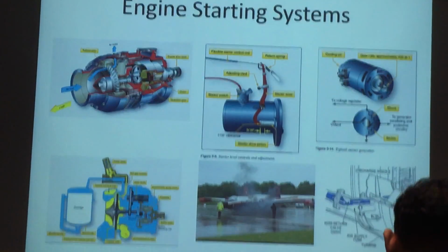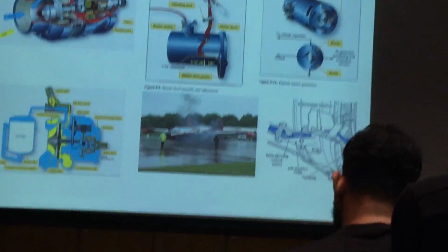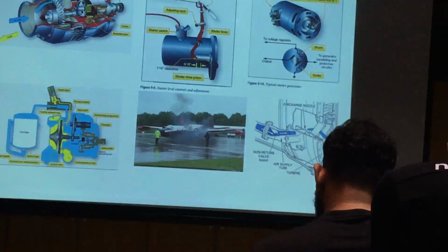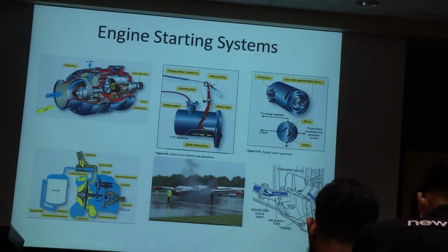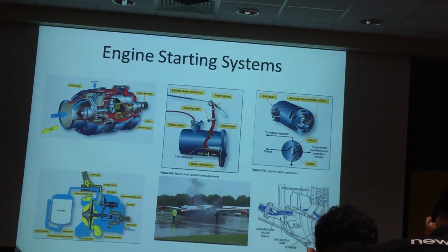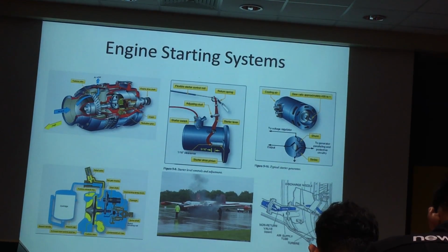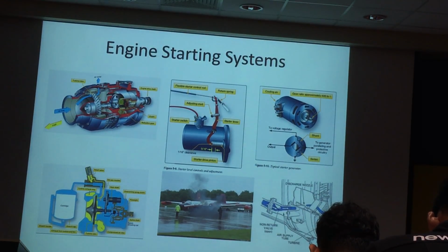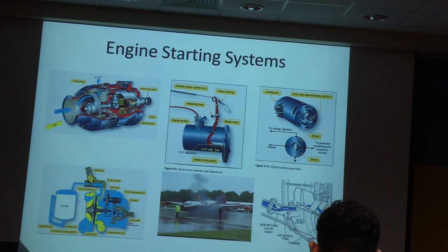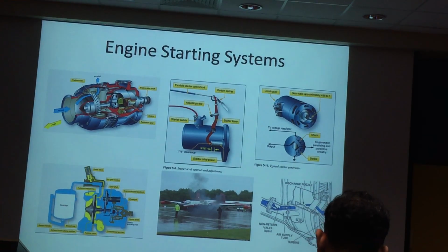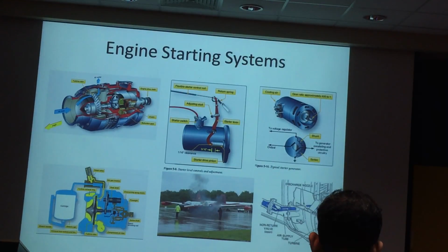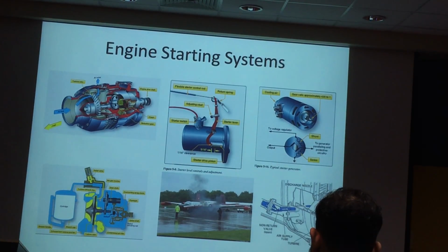Okay? So come to the auxiliary power unit. There's one unit the aircraft carries on board, which we call the auxiliary power unit. It's actually a small engine that runs during ground operation to supply 2 things. What are the 2 things? Pneumatic supply and electrical supply, okay? Because on the ground your aircraft is waiting dead, you need pneumatic air and electric. This will come from your auxiliary power unit. If you don't have an auxiliary power unit, you need a ground power unit. Sometimes the A stands for auxiliary, sometimes people call it airborne power unit.